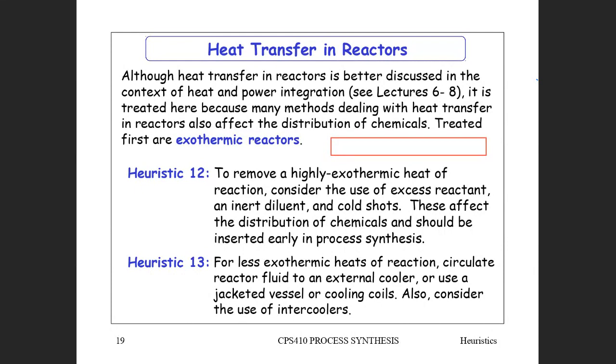You can put in your feed over there, and then the reaction will heat up because of the highly exothermic reaction. Then you put in some more cold feed over here in the middle of the reactor, and some more all along the reactor, and that's called cold shots.